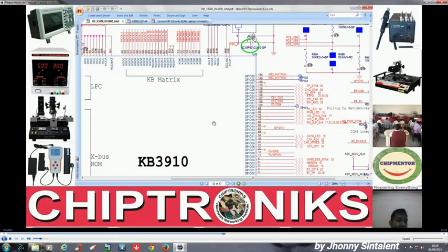You may find cases where this same IO controller is used in a different motherboard, and pin number 118, which you see configured as output here, may be configured as input there. It is 100% possible because these are GPIO, general purpose input output pins.